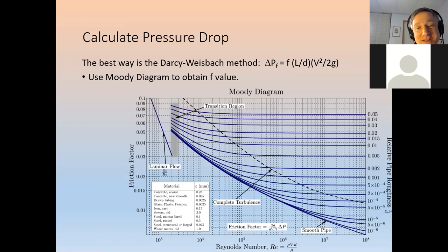So that's where this comes in. You want to push an airplane through the wind. You want to push a car through the wind. You want to have air flowing over a heat exchanger to improve convective heat transfer. So you want velocity. And that's where then we look at, okay, what does this mean? Well, we're saying then this laminar, you get these higher numbers because you have, we'll say, this thick, low velocity part of the boundary layer. And then you trip into turbulent boundary layer.